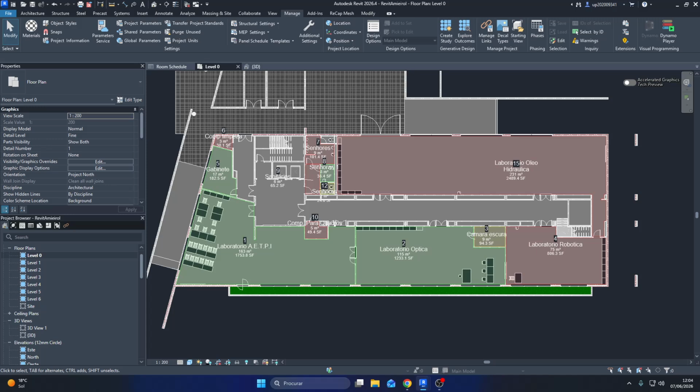The main limitation was the automatic creation of parameters, as I said before, because the tested Archilab nodes produced compatibility errors. For this reason, the parameters were created manually in Revit while the data population process was fully automated through Dynamo. Overall, the work shows the potential of BIM models as database platforms where external data sets can support classification, analysis, visualization, and decision making.